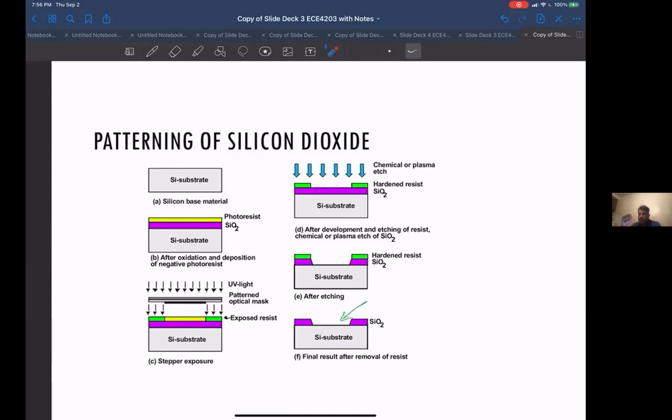The manufacturing plant has a few tools: implants, etch, lithographic patterning. This is for the silicon, so the transistors are all in the silicon. All they have there is implant, etch, oxide deposition, and the patterning of these patterns. That's all the tools they have in hand.